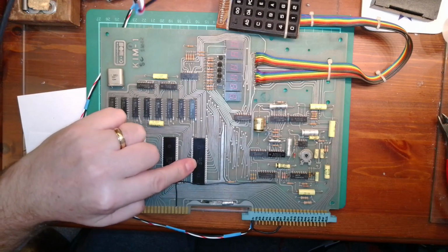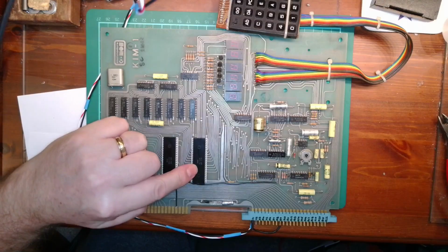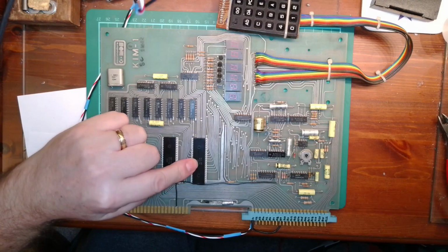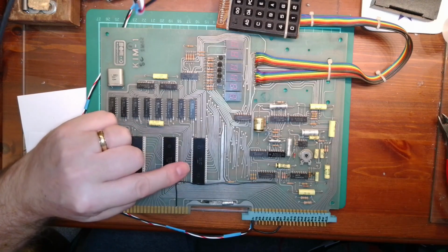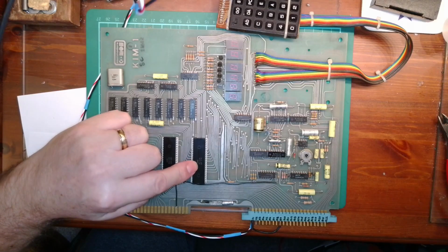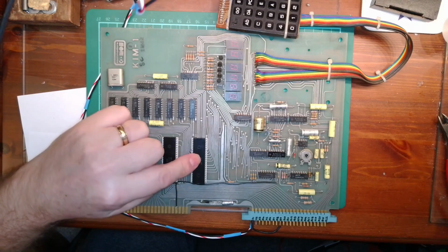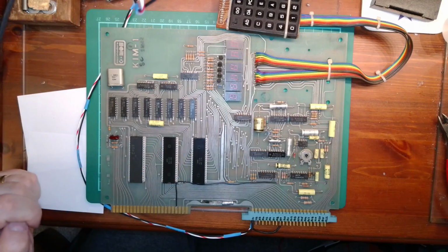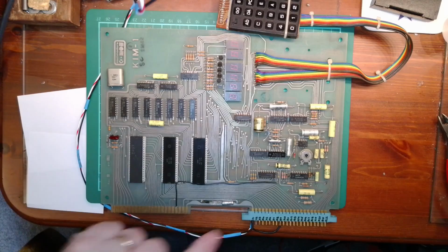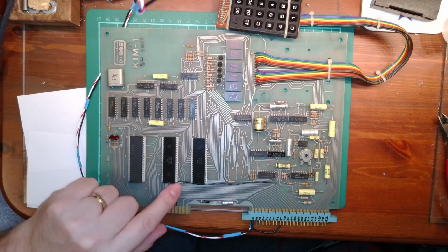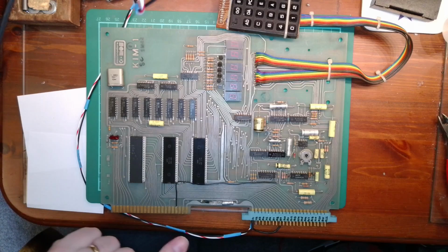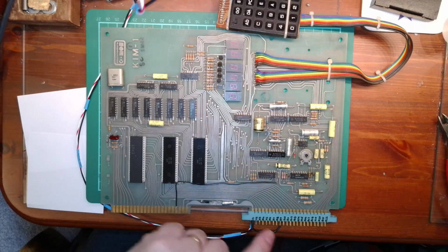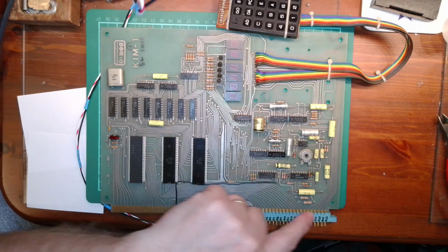So this is all configured in the board. So this chip here is actually the lower ROM space, or one of the lower spaces, and it actually repeats itself higher up, so we can get the address vector out of this IC here, which is in fact lower down in the actual memory addressing. Now that is this wire link here, this black link you see, that I put over there to get it all to run. It's only on that side.